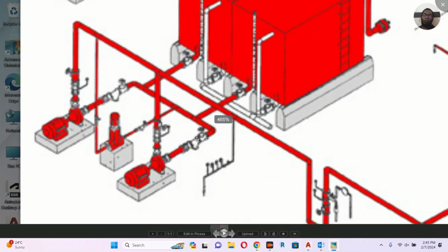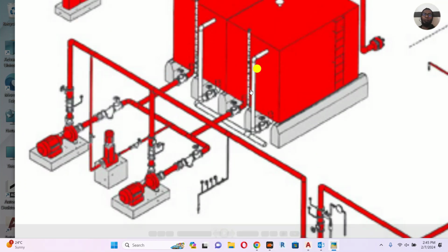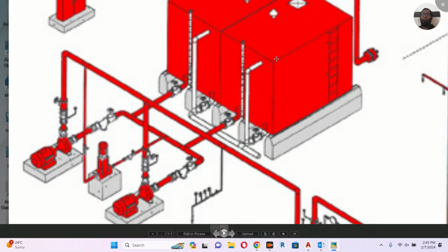So here what we have to do with the fire alarm system, let's say the one we have to monitor the water tank, whether there is enough water or not. So we have to always monitor that one. So we can provide one monitor module there. The second thing, the valve should be monitored. Maybe some guy comes and closes the valve by mistake. So this is a problem. When fire happens, this valve will be closed, the water will not come. So always the valve should be in the open state.